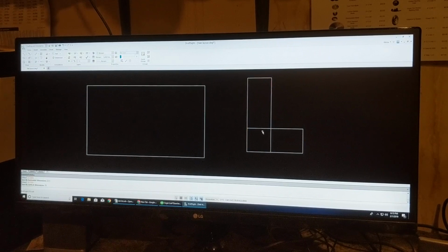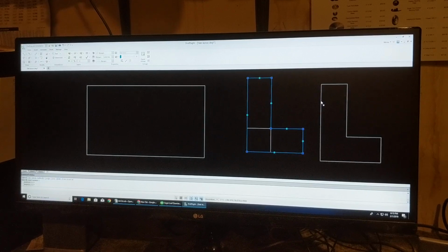Right now this is two separate rectangles, which can make it kind of tricky to move. You come back up here to the same little thing. There's a function called polyline, and that's where you can build your own line. So I just go through and I select all my points and intersections. There's the last one, so I just hit C for close, and there's my vanity, all as one piece. I can delete those, I'm done with them.